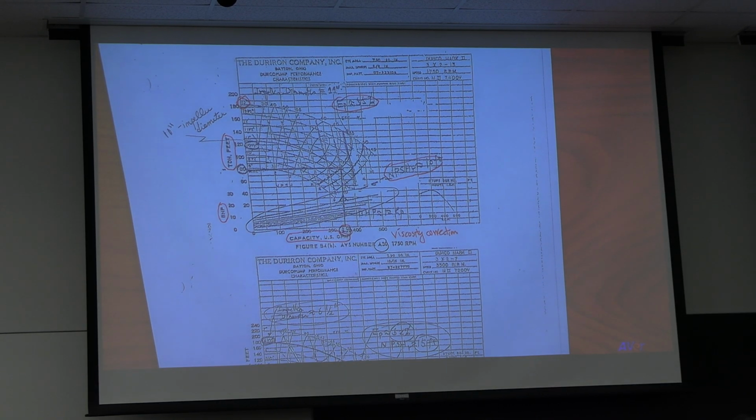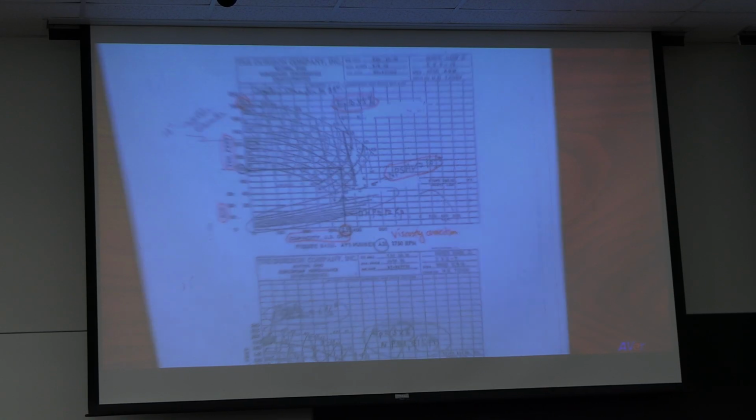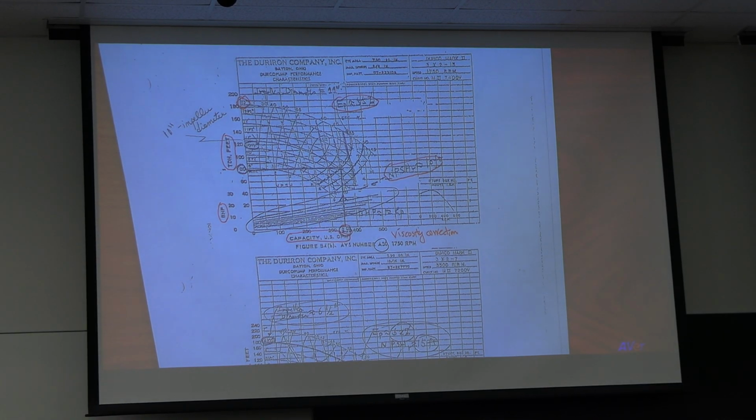He gave you 300 gallons per minute. What else do you need to ask? Differential head? No. I'm talking about the physical property of the liquid being pumped. Now, this is an important question. You immediately ask two questions. Otherwise, you cannot continue your work.